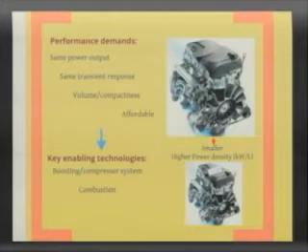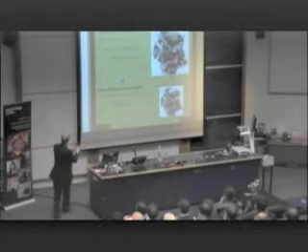So what have I done? I've made it smaller. So what? Well, suddenly, I might have reduced the number of cylinders from 6, likely to be, to 4. I've reduced the capacity from 3 to 1.4. And in doing that, I've reduced friction. These cylinders, as they move, and you'll see in a minute, produce friction. The valves are opening and closing. You will see those too, friction. All the drivetrain system, and particularly the engine system, all has friction. So I have reduced the size of the engine. I've reduced my friction.